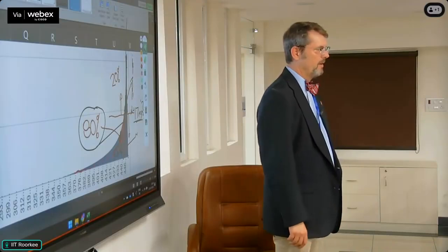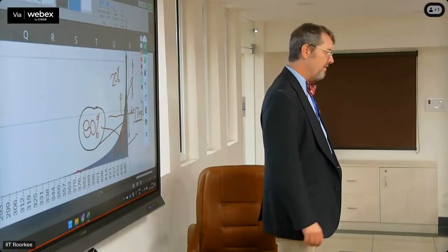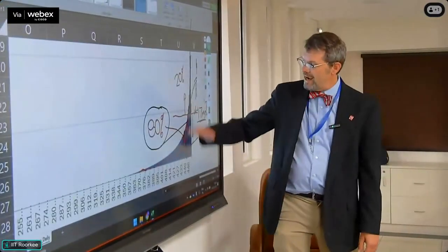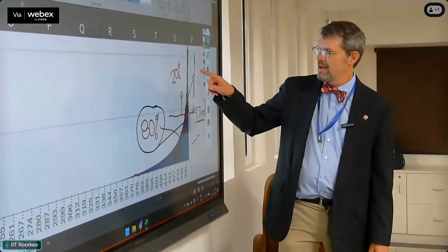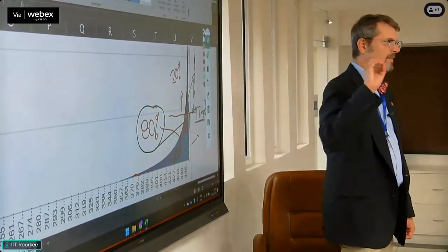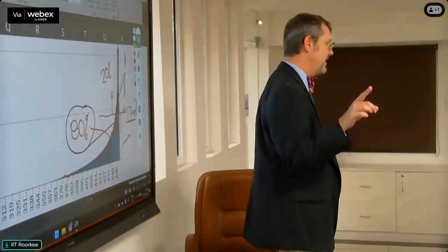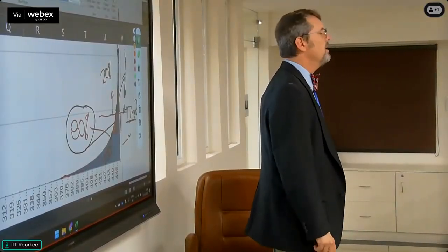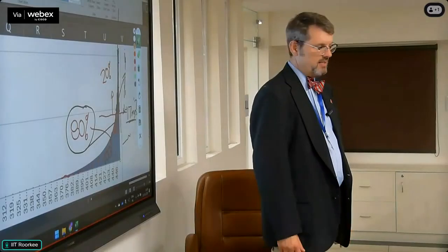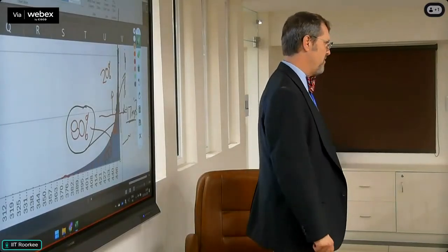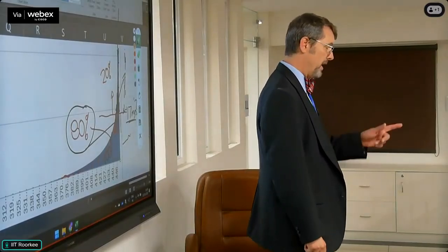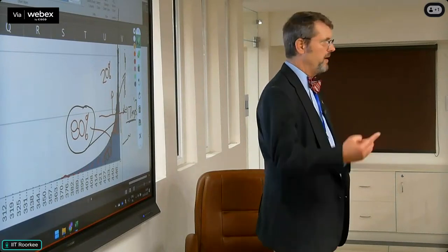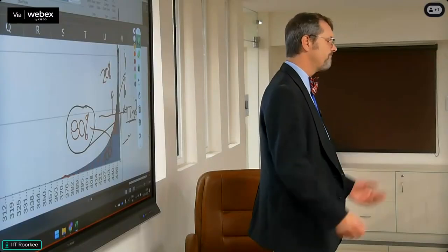And so with the data that you have, what I'd like for you to do is figure out what value gets you 80% subject to treatment and 20% bypass. And from what we said, 17 is too low of a number. It's going to be actually a fair amount higher. And I had suggested to Vienarossi that maybe the number is about 30 millimeters, which, by the way, is in line with a lot of southern states. 1.2 inches is right at 30 millimeters.